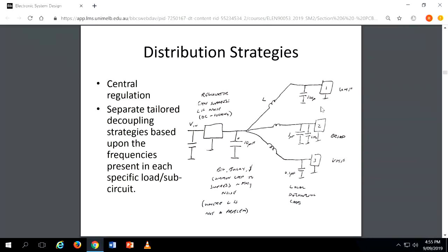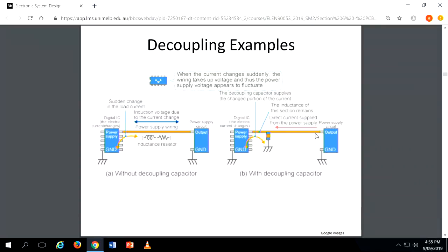Then if you have an analog part, and again a digital part, or low frequency, different domains, different types of circuits, then you can have a ferrite bead for the power supply, because then this switching will not come to this part and couple to your analog part. Maybe this is a digital part. That also we already discussed. Then this is another example.